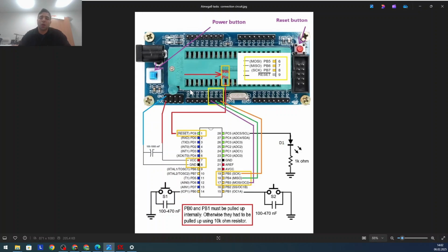You don't need to put any extra wires for the programming. But now we want to program the Atmega 8. The other was Atmega 32. Atmega 8 is a small chip. It will not fit here, and the pin layout is totally different than Atmega 32.